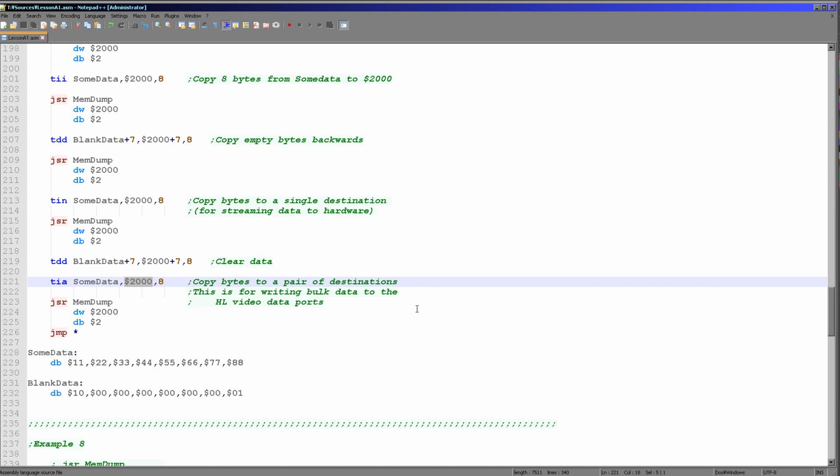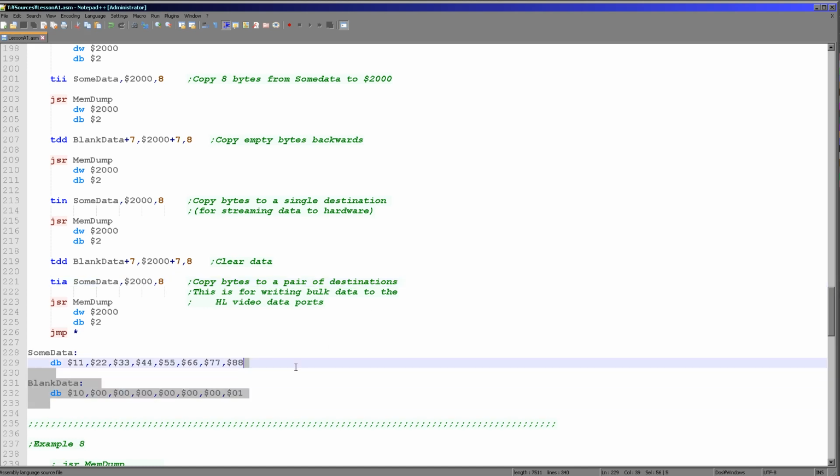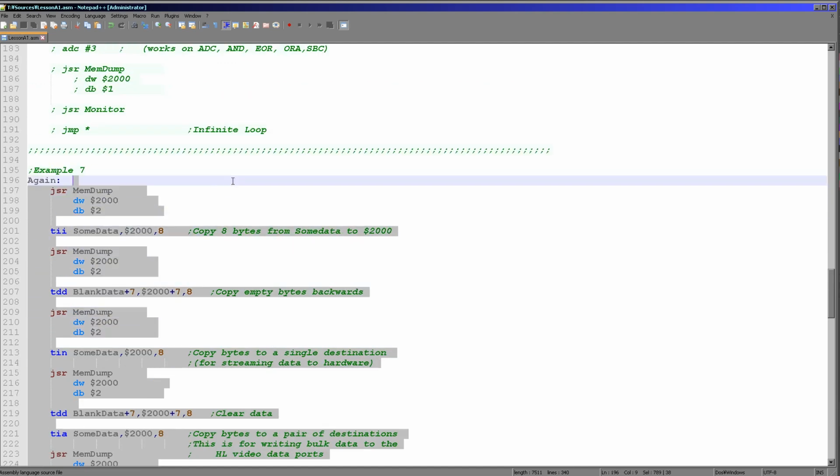With regards to the fonts within my examples here, I was actually converting the fonts from 1 bit per pixel to 4 bits per pixel, so it wasn't possible to use these commands because I needed to actually do mathematical operations on the byte data first. So clever and powerful commands, but may not be useful depending on what you're using them for.